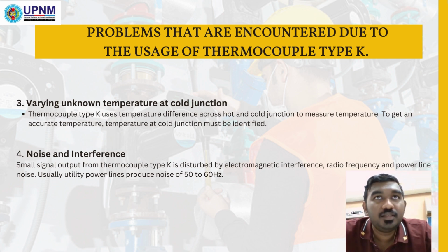One common method is the cold junction compensation technique. This involves measuring the temperature at the cold junction with a precise temperature sensor, such as a thermistor or RTD. The measured cold junction temperature is then used to correct the thermocouple voltage reading. This correction is applied by adding the voltage equivalent of the cold junction temperature.